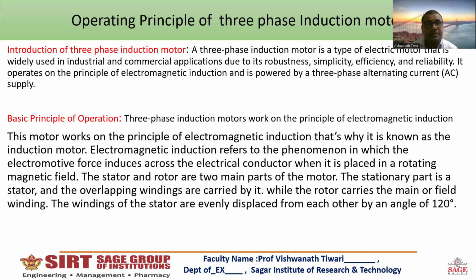The basic principle of operation of the three-phase induction motor is based on Faraday's law of electromagnetic induction. This motor works on the principle of electromagnetic induction, which is why it is known as the induction motor. Electromagnetic induction refers to the phenomenon in which an electromotive force is induced across an electrical conductor when it is placed in a rotating magnetic field.